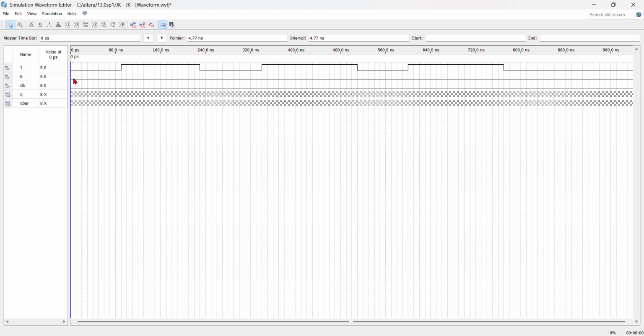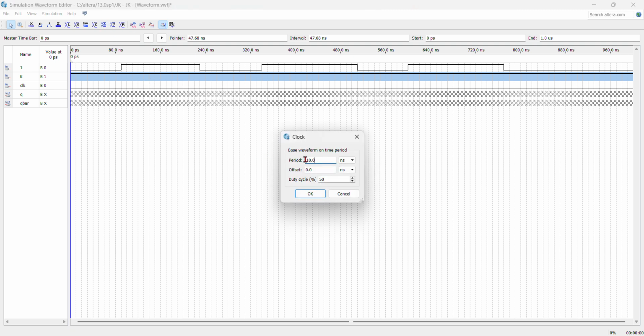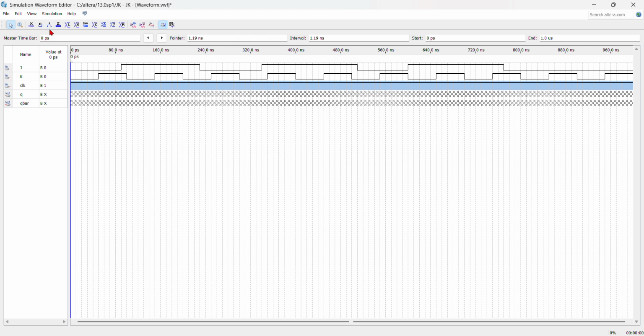Now I'm going to select this one with the frequency of 100, which has 0 1 0 1 0 1, and I'm going to give the clock signal as entire one. Once we finalize the inputs, we should run this waveform diagram.